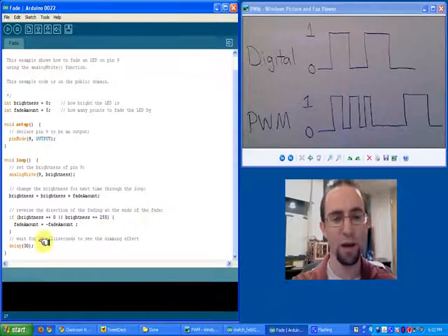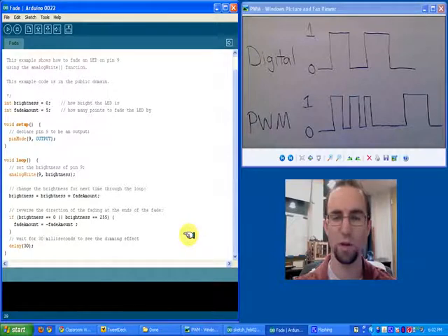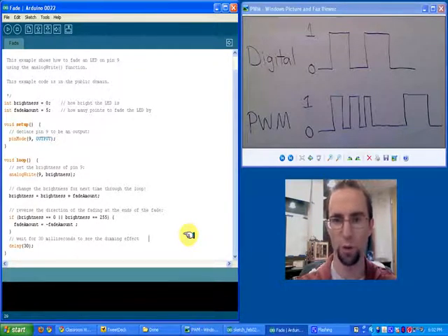So at the end is the delay of 30 milliseconds, and that is once again just, even though it's a really small delay, it's to make it so that our eyes can see it. Otherwise we would just see this constant on, because the pulse width modulation is going so fast. So we delay it by less just because we're doing a pulse so quickly, but we still need to delay it.